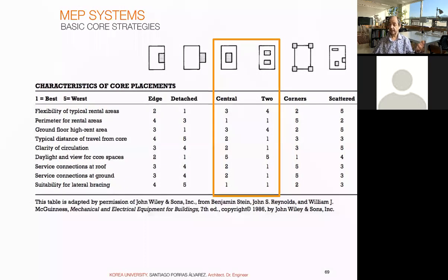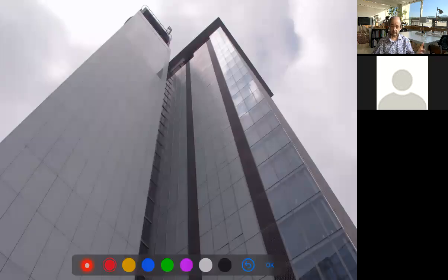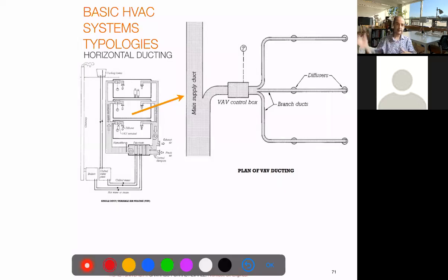As an example, again, KT Tower in Gwanghwamun has an outside core. So the office space is almost free of anything else but office space. So we know the position of, we decided the system we use for the mechanical system. We decided the position of the fan rooms. We decided the kind of position of the air handling units, the cores and the shafts.